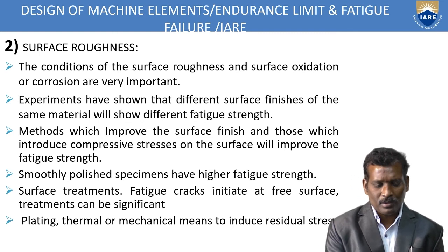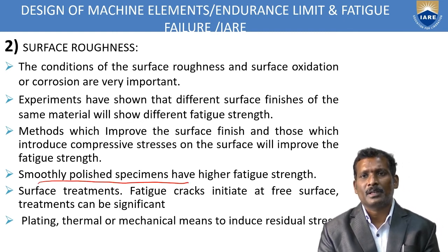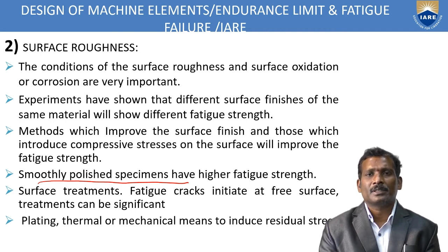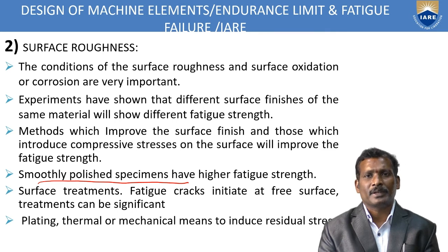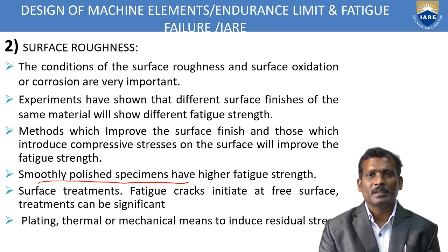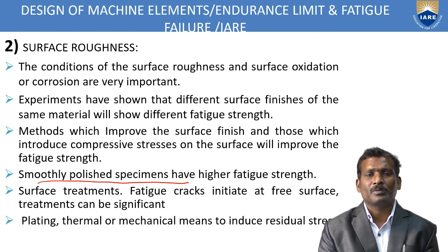And smoothly polished specimens, as I have already shown in the previous slides, have higher fatigue strength. That's why we test polished specimens for fatigue strength calculations. For surface treatments, fatigue cracks initiate at a free surface, so surface treatments can be significant. And plating, thermal or mechanical means introduce residual stresses. Some residual stresses also cause fatigue failure.